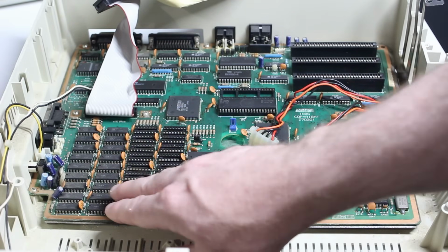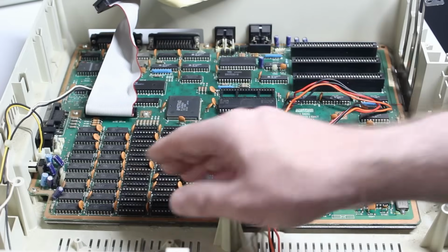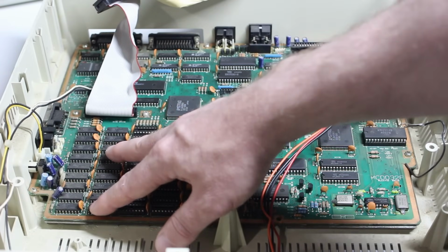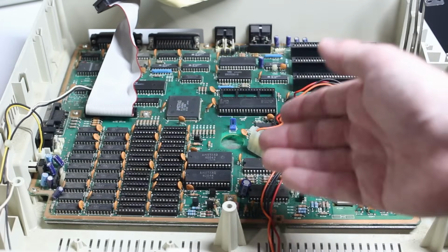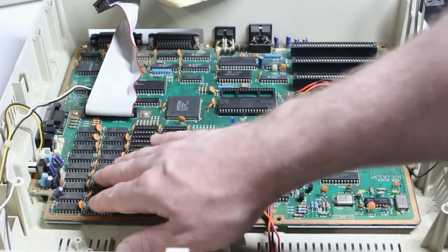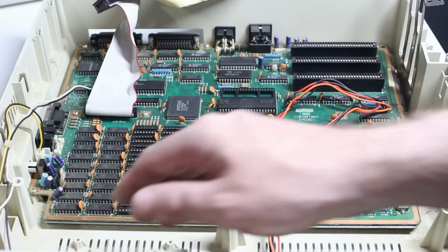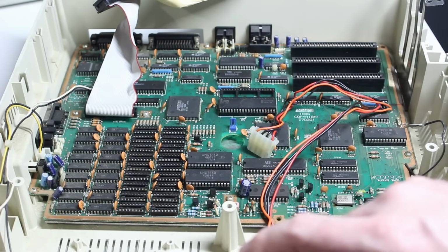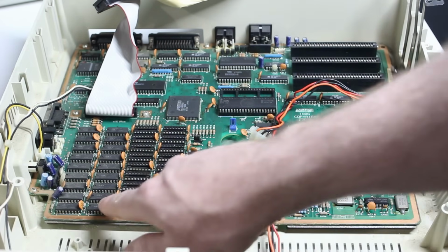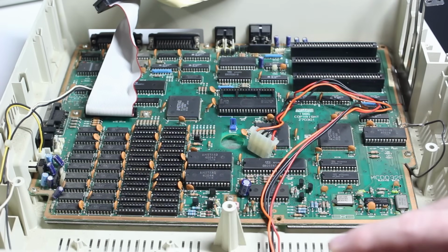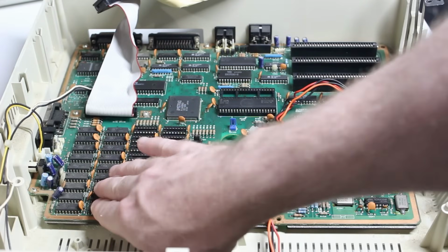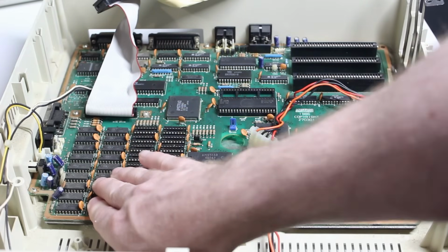Now, we're going to try and turn that pulse off, if it's even possible with this machine, and do the dynamic RAM refresh ourselves so that we can get cycle accurate timing of the machine. And that's why I need to know how often that pulse occurs. It turns out that these require refresh every 4 milliseconds. Now that's a little bit more often than 4 times per graphics frame. The monitor of course runs at 60 Hertz. So that's the critical information that I need about these chips.